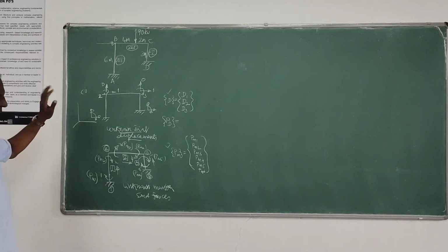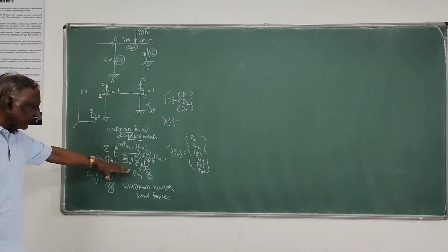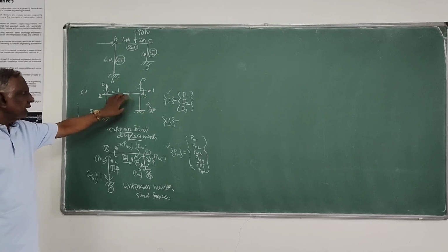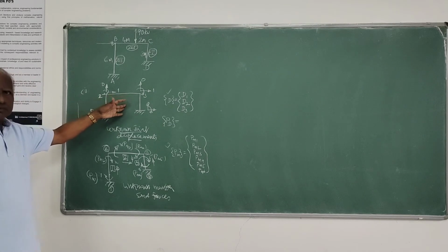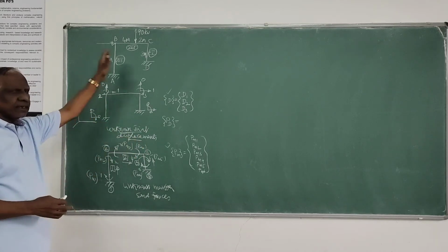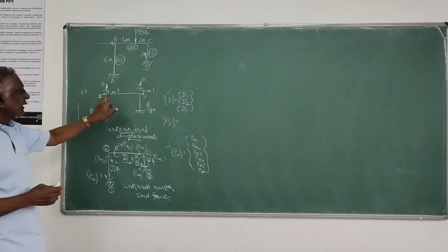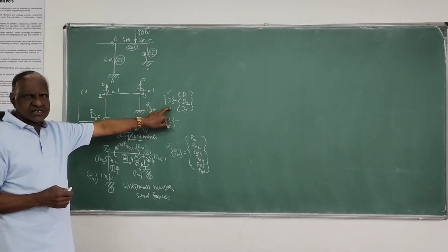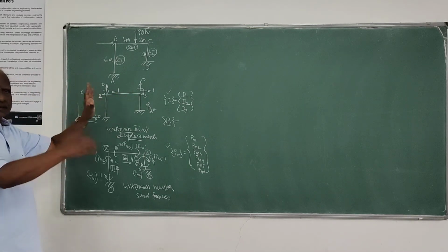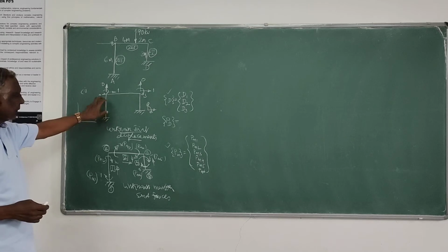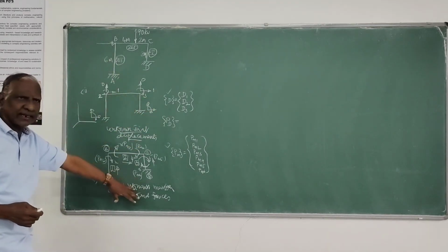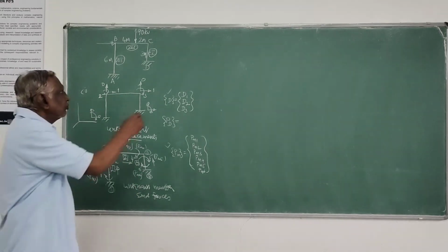That's the first step. One is in global coordinates, another in local coordinates. This displacement we determine by using the force displacement relationship first, that is P is equal to KD, where K is the global stiffness matrix in terms of the coordinates selected for D. So here 3 coordinates are there. The global stiffness matrix will be 3 by 3 for finding displacement. First we have to determine displacement, and then we determine the member end forces.